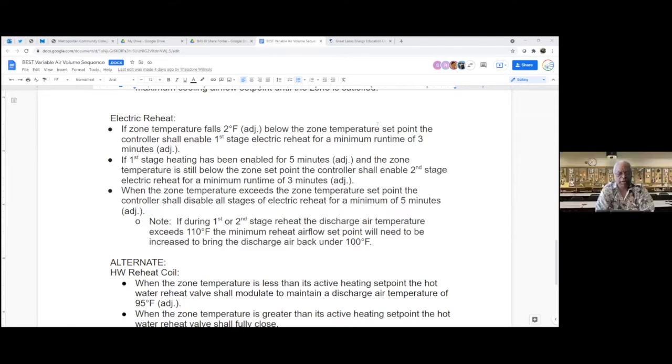Well, can I also say that this is a great discussion, but it's going to take all morning to really sit through. The ASHRAE code is 62.1 for commercial spaces. Those numbers that are being mentioned depend on occupancy and some other things, but that's a ventilation air. That requirement is an actual CFM of outside air.